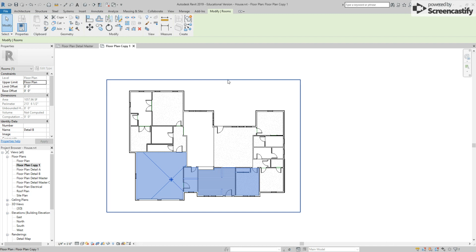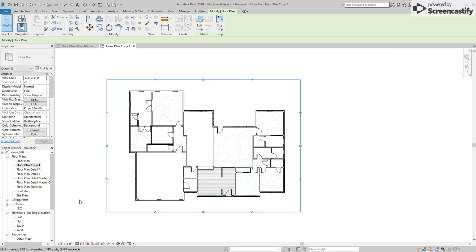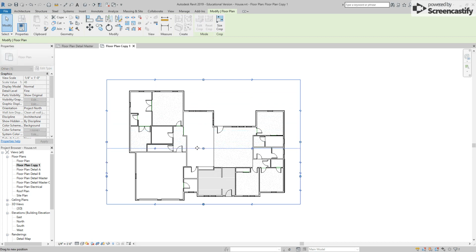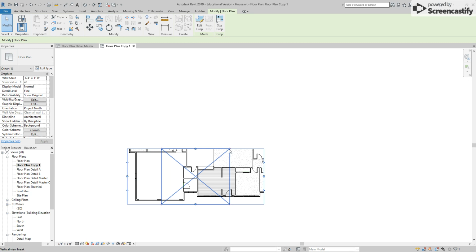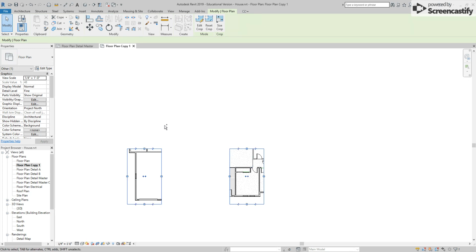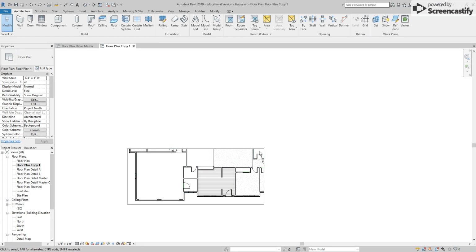I'm going to click my highlighted area now, zoom out, and click my crop window. If you're not seeing the crop window, it is right here in the small menu. I'm going to use my cropped window to crop it down and only show the area. You will likely see stubs of walls or small sections that you're cutting out. There are ways to turn this into a different shape, but we don't really need that for our purpose. Cutting it to look like this will be just fine.